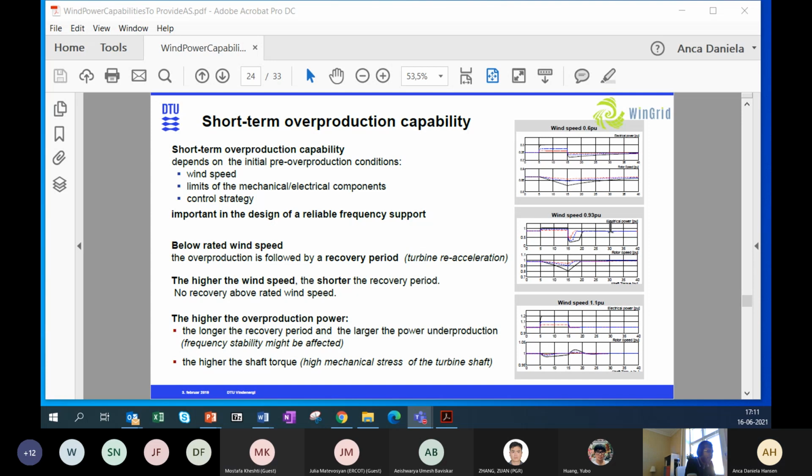In a large wind farm, you do not see that fast ramp. Even a fast ramp gust for a single wind turbine is probable, but not for a wind farm. So I don't think you would see that kind of difference for minutes. Yes, for sure. You also have to remember that there is smoothing at the wind power plant level as well. So what you see at an individual wind turbine is not what you see at the wind power plant level.